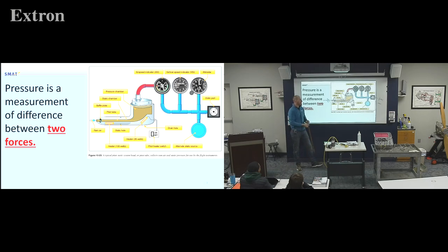But say you do that, we run a vacuum on there, and plug the line off, and then my altimeter starts saying, you're falling. Basically, the pressure is coming back into it, right? Well, we have a leak in our system somewhere. A lot of times you assume it's going to be the hoses, but it's usually the aircraft. So we're going to show you how to deal with that right before we go to lab, when we go to break. Making sense so far? We are going to loop back and do this practically like 3 times with you later in the day.